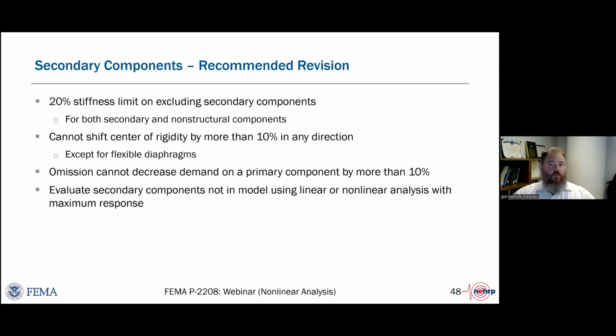Now note that these are all things that can be checked in a linear model. So you can use your linear model to iterate on these things to determine what is going to be the best use of your time in building the nonlinear model. Once you've chosen to build the nonlinear model, you do still have to check deformation compatibility, and we provide recommendations on how to do so.